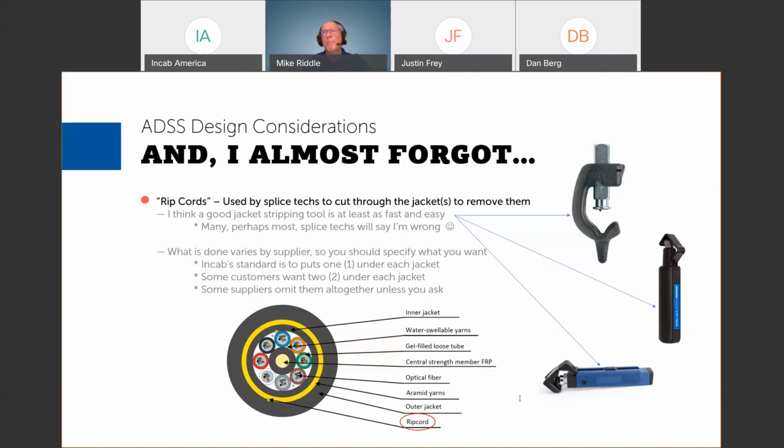It's kind of beyond the scope of today's discussion to go into elaborate detail about this, but the problem with the wedge dead end fundamentally is that, remember I talked about you have to couple the tension in the cable to the structure, and you're doing that through this mechanism called the dead end. With a formed wire dead end, you're doing that over the entire length of the rods. Now, the dead end suppliers will say it's really the first, I don't know, 2/3 of them or whatever, and the rest is kind of margin for error or for other purposes. But still, the point remains.